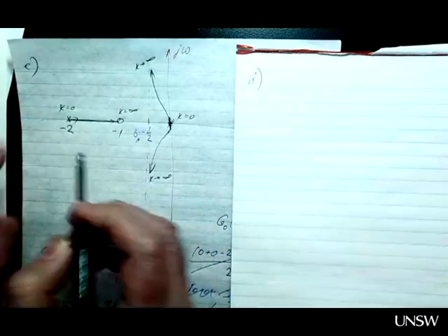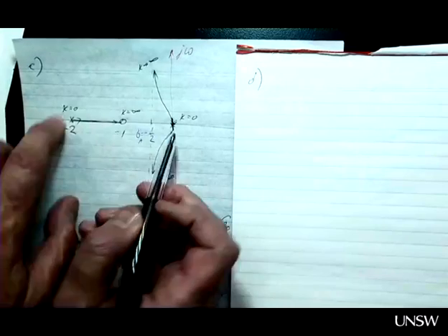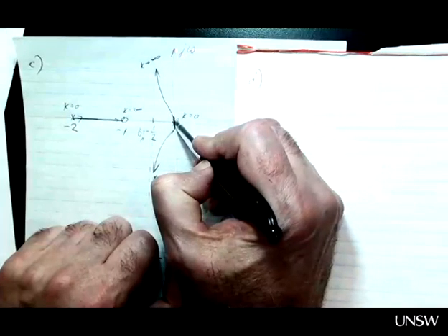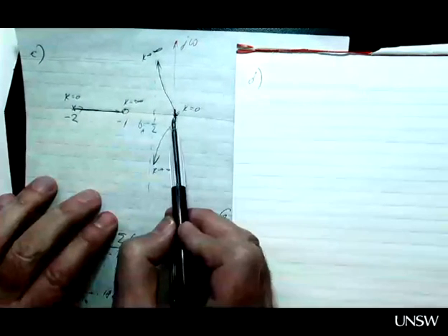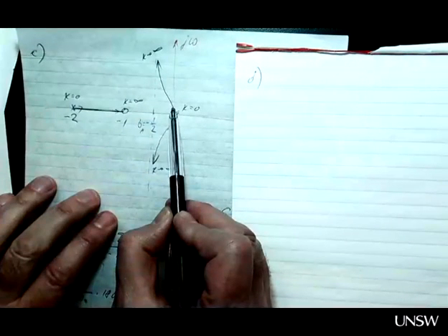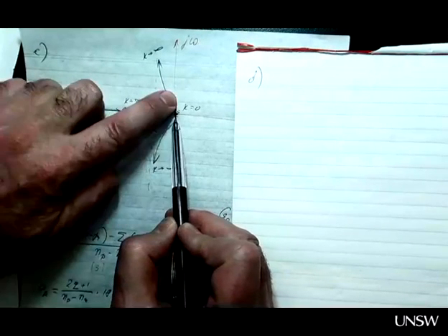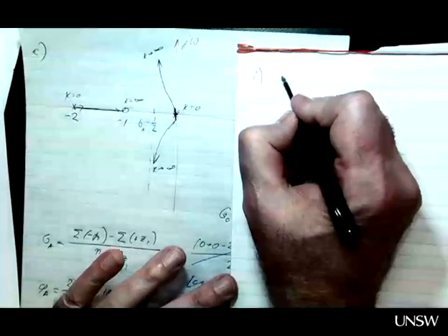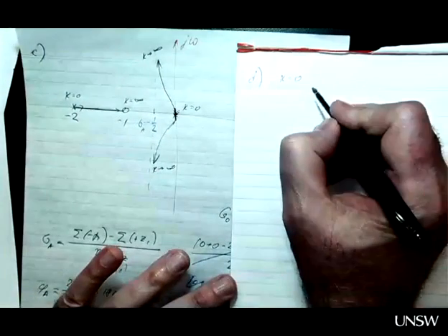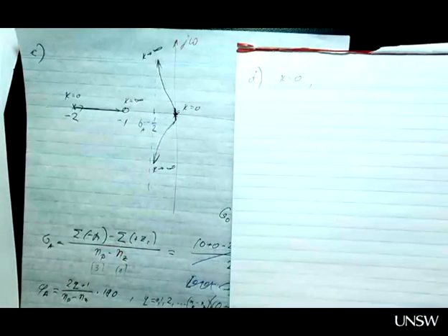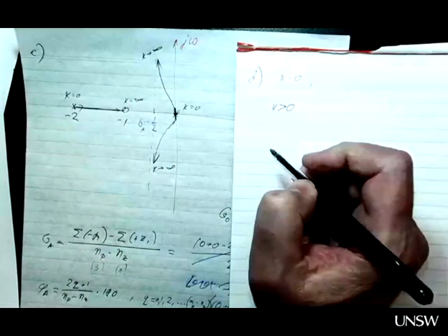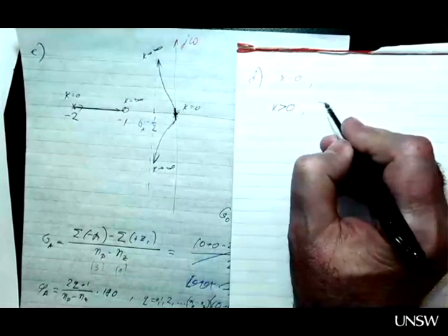But these 2, initially, they are both on the real axis, meaning non-oscillatory behavior. As soon as K becomes greater than 0, you get a pair of complex conjugate poles. So for K equal to 0, you have non-oscillatory behavior. For K greater than 0, damping ratio becomes less than 1, greater than 0.